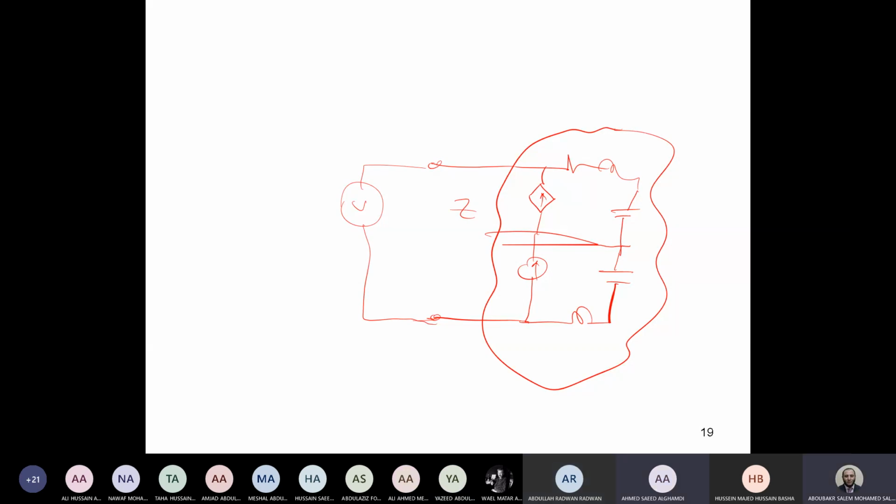Did you do it like that in the Thevenin calculations? I believe in a Thevenin calculation, guys, if you have dependent sources like that, you cannot achieve the equivalent impedance directly, I mean mathematically. You have to first calculate V open circuit, then calculate I short circuit. Is it right? Yes, this was one of the methods. And finally, we get Z as V open circuit over I short circuit. Okay? This is if the circuit is complex, guys. The same applies in our machine.